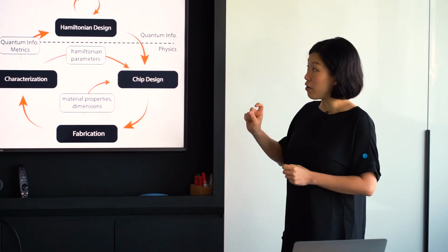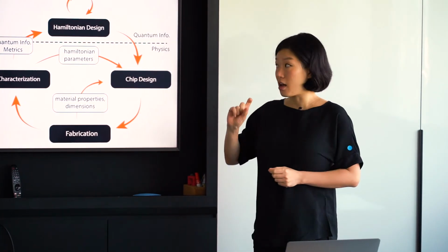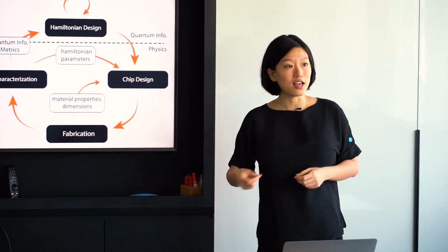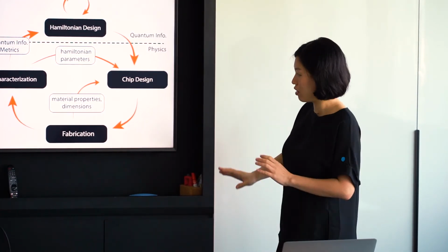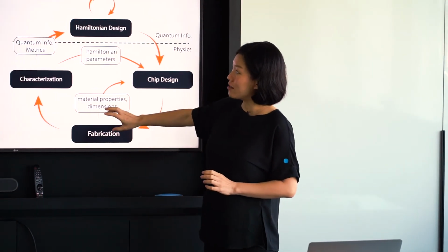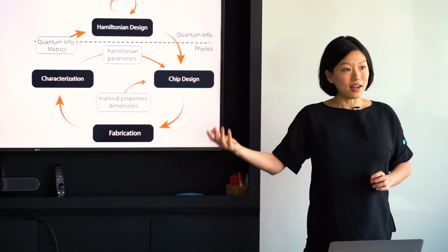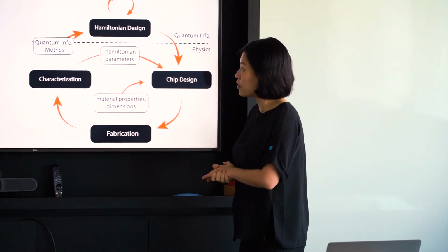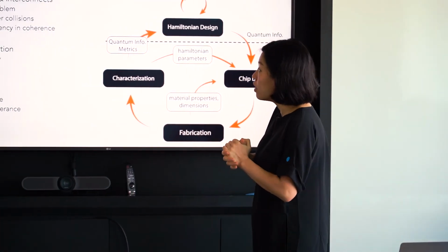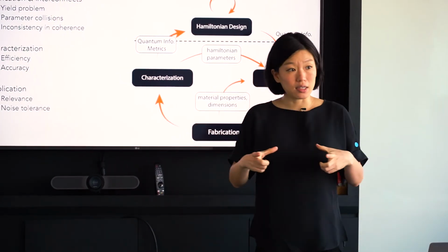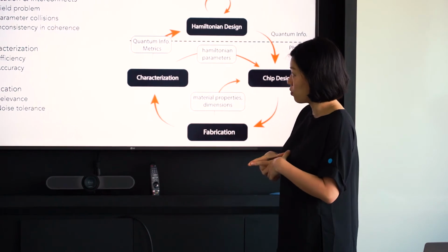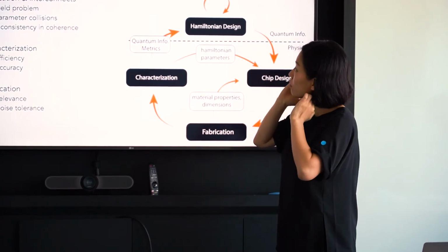This happens at a very low percentage these days, like 99.9% of the time we get the device that we wanted, at least on the fabrication level. But imagine if you have 1,000 times that, then the 0.1% of not getting that could become very much amplified, right? So yield could be a problem when we're thinking about building devices, thousands of them on a monolithic chip, that we're seeing right now.